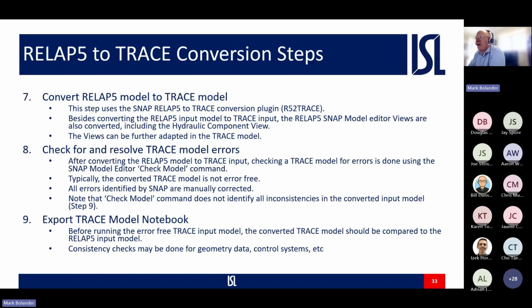And then you can go in and convert your RELAP5 model to TRACE. This step uses the conversion plugin, as we've pointed out earlier. Besides converting the RELAP5 input model to TRACE input, the model editor views are also converted, including the hydraulic component view.